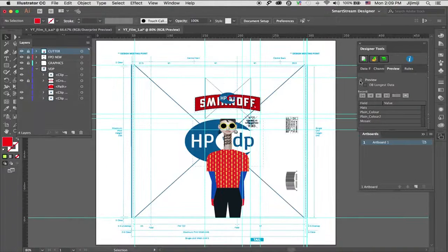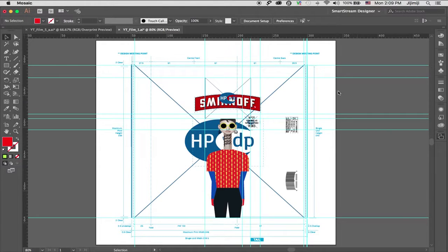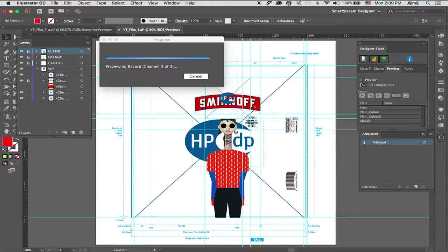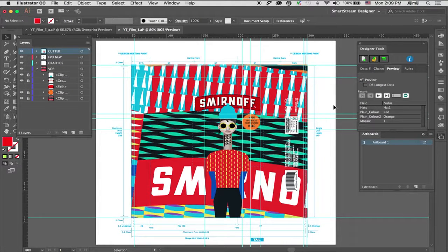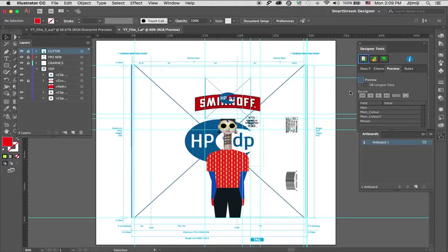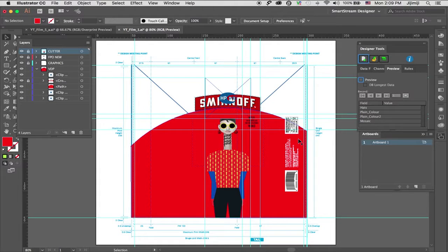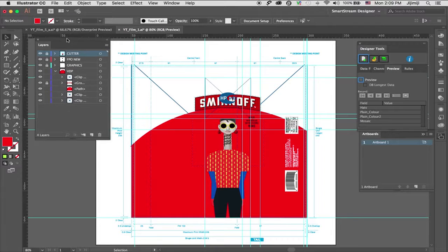So now that we've set up our Mosaic background, this is how it looks. Now I want to use another Mosaic channel and override it. So we'll have 2 Mosaic channels altogether using the same seed files, but with different parameters, which will give us a totally different look. So I created this path over here, and this is where I want the second Mosaic channel to reside. So I'll just remove this background color.